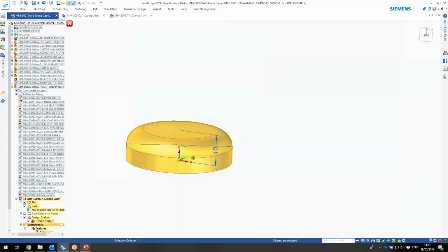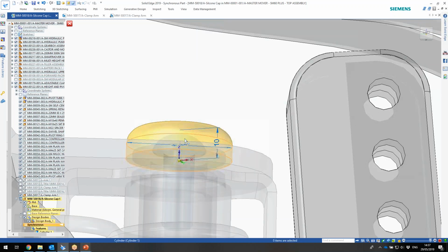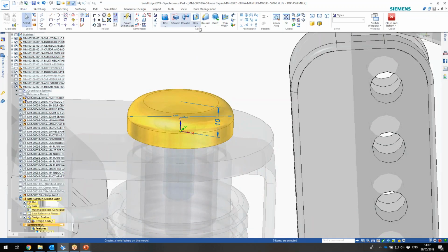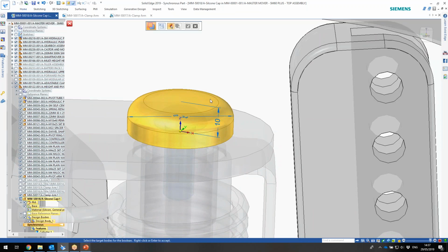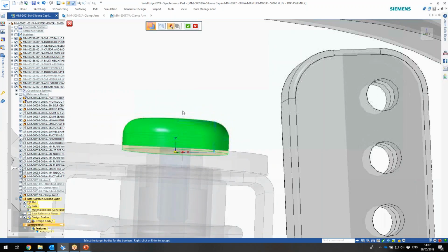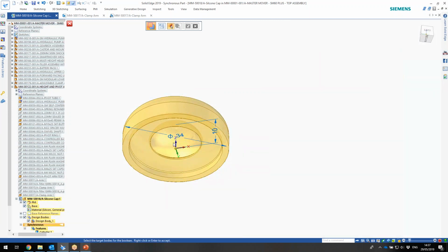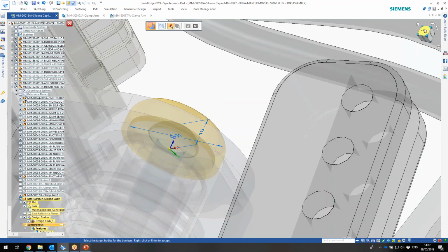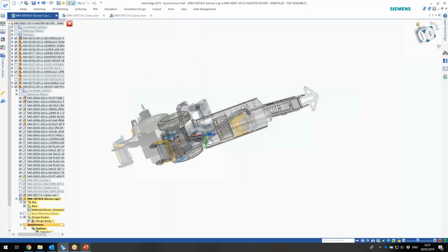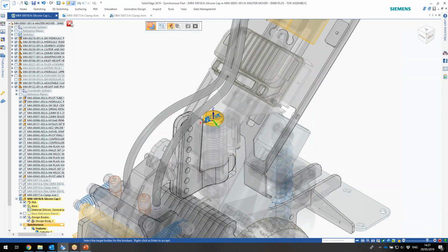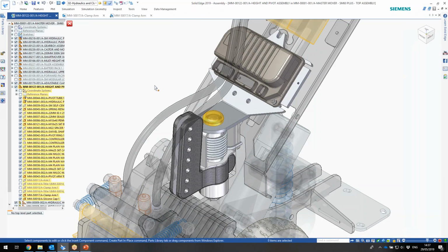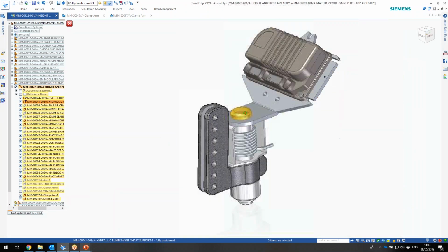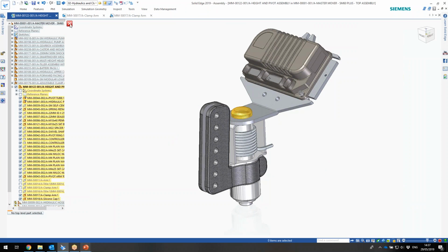And currently this is a solid model, so we need to cut out that rivet and the washer from the bottom. So we want to go home, subtract. So we want to subtract from this part. We want to subtract the rivet and the washer. Done. Control Q, and now you've created a snap washer that'll fit over that rivet and washer right first time. Jump back out into the view, and we'll close that. Now I have a cap over that clamp arm, and we'll go close this view as well.